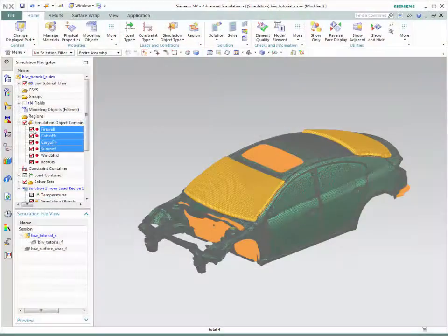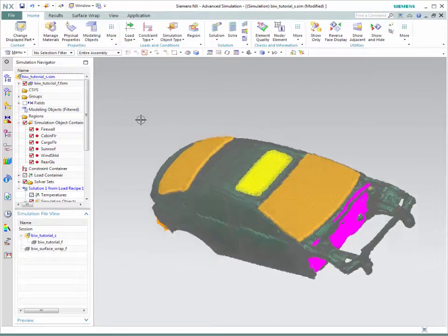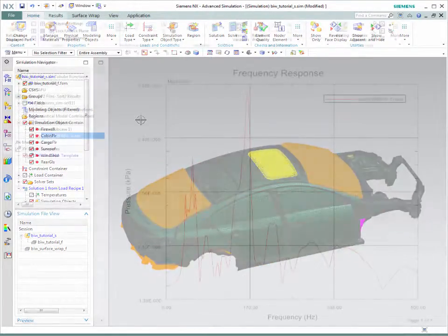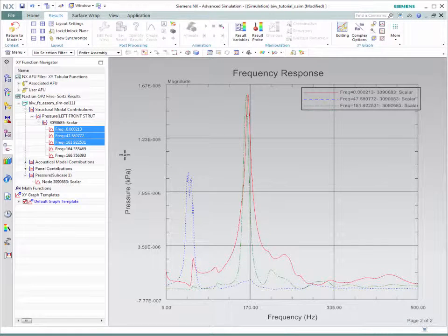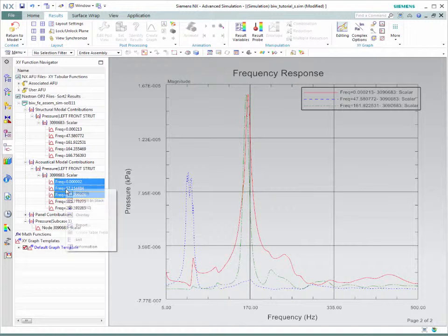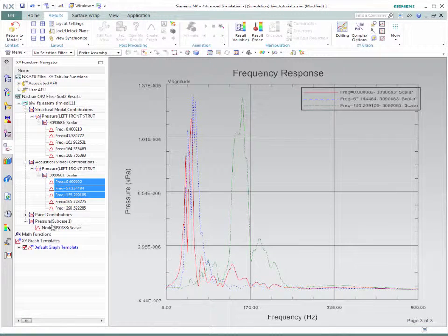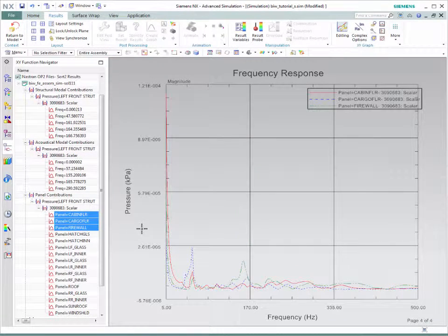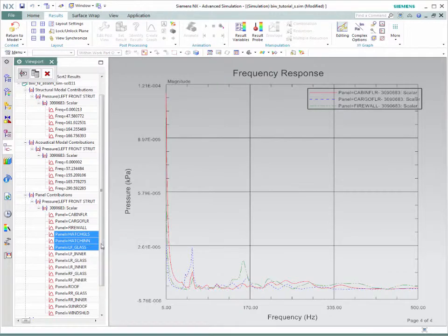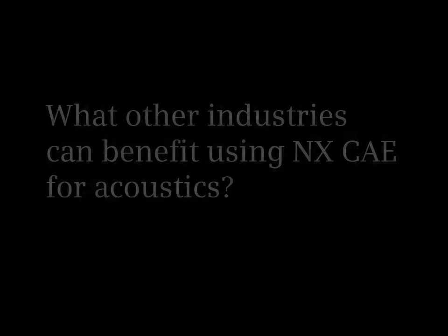We actually support the panel and mode contributions now in NX. So the post-processing capability has that panel and mode contributions. It's going to give you all the results from master. Typically automotive use cases is that one would be interested in looking at the response of different panels, or the contribution from a different panel at a given location. So there's a response point, and if the panel is contributing more, then you could actually reduce it.